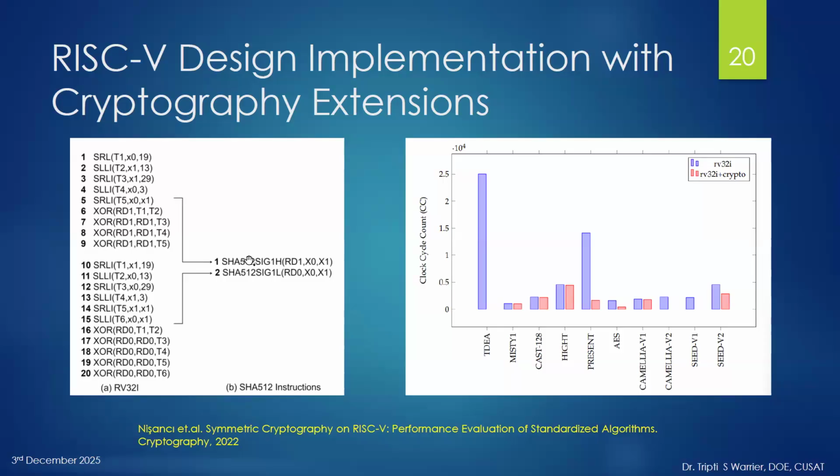this instruction will be executed inside the normal pipeline itself. If the clock frequency doesn't change by including this instruction, then when the instruction count reduces, performance improves. The number of clock cycles to execute the same program reduces, and when clock cycles reduce, performance improvement happens automatically.